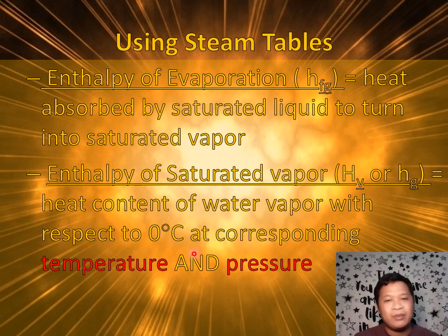So anyway, ang enthalpies kasi is initial and final states yan. Usually when we consider enthalpy problems, we consider the initial and final state and use these points to compute for the change in enthalpy. So for example, if you heat water from 30 degrees Celsius to 90 degrees Celsius, to get the change in enthalpy, you just subtract the one enthalpy value from the other, and you have to determine those using the table, sometimes in interpolation.